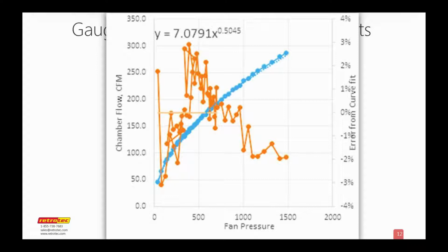From what I've been told, talking to people that do the calibrations, they say that gauges basically either work or not. They need about a 10% error in a gauge. A 10% error in a gauge will actually cause about a 5% error in a fan. So the gauge is usually the strong link. That means that it's almost a factor of 2 to 1 of how much better it is, or how little it actually affects the actual overall system performance. So this test that we're looking at here shows a pretty accurate test.